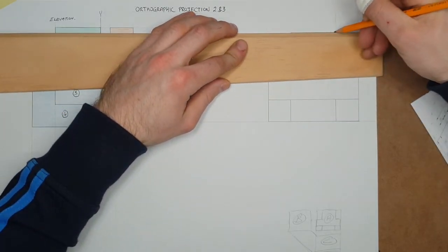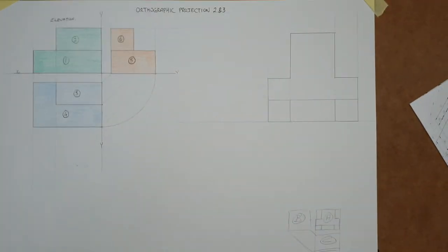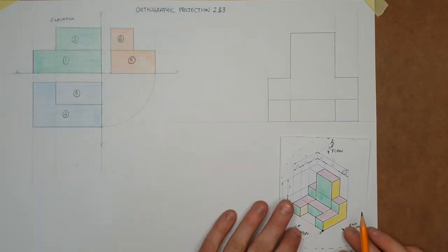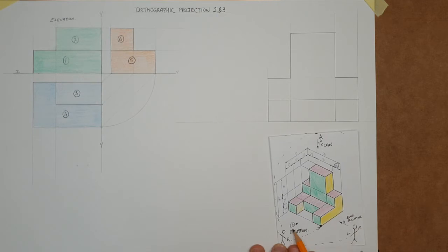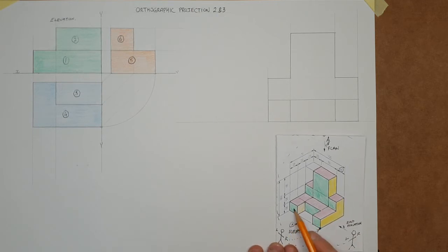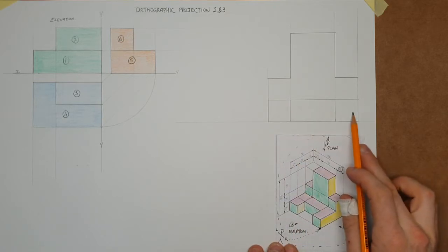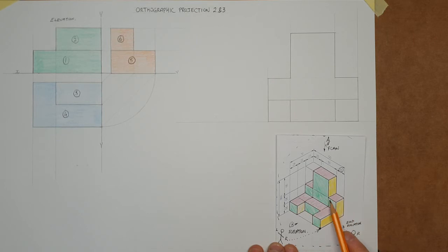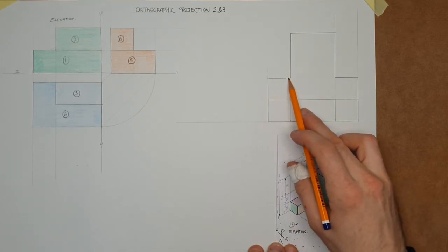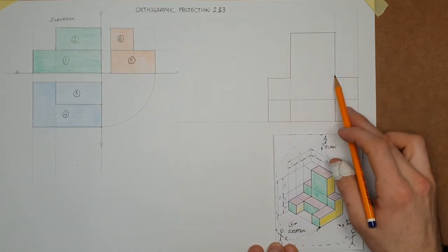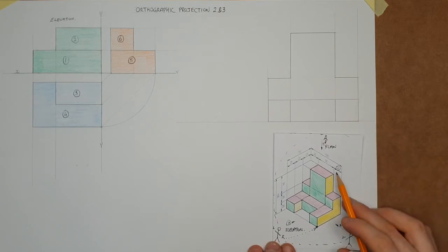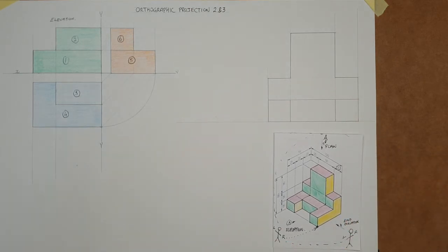Finally, top of the object. Now, everything we can see from position A, looking in, being the left 25 mil, the middle 50 and the right 25. Left 25, middle 50, right 25, and then this guy right here. This top one, 25, 25, 50, 50, 50, 25, 25. Just like before, I'm going to take just a minute there, pause the video, add a little bit of green shading in on this surface, and move on from there.